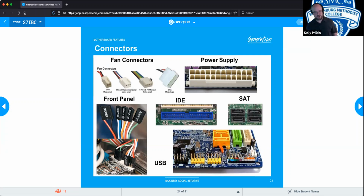Hint, you will probably hear that question again. So if you only have 3 pins and a 4-pin connector, you go ahead and plug it in, because the only thing you are going to lose is the speed of the fan, but you'll still be able to turn it off and on to cool the CPU or the computer.